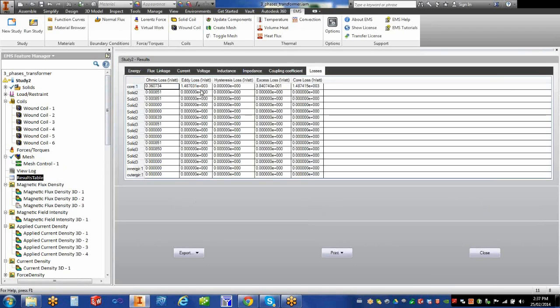Physicists break the core loss down into three types of losses. One is the eddy loss, which is clear. Hysteresis loss is clear. And there is another part which is neither eddy loss nor hysteresis loss, so it's called excess loss. The core loss is really the sum of the three of them. That is the excess loss: some other mechanism of losses different from the eddy and hysteresis losses in the core. Does that answer your question, sir?